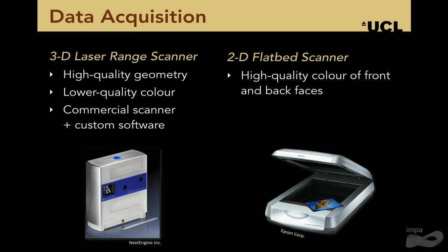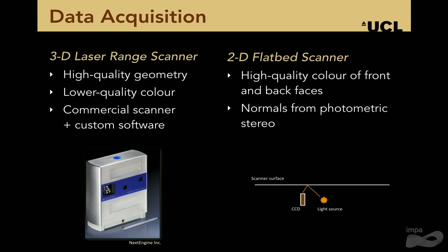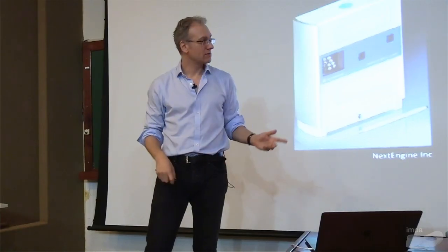And it turns out you can also use a flatbed scanner to reconstruct the surface structure. That is because in every flatbed scanner, you have a linear camera, essentially a linear CCD array, and you've got a light source to illuminate the document that you try to scan from below. Now, those two cannot be in the same position because either would block the other one, so they need to be slightly offset with respect to each other. But that also means that this imager sees every surface point illuminated under a slight angle. So the light always comes from a slight angle.